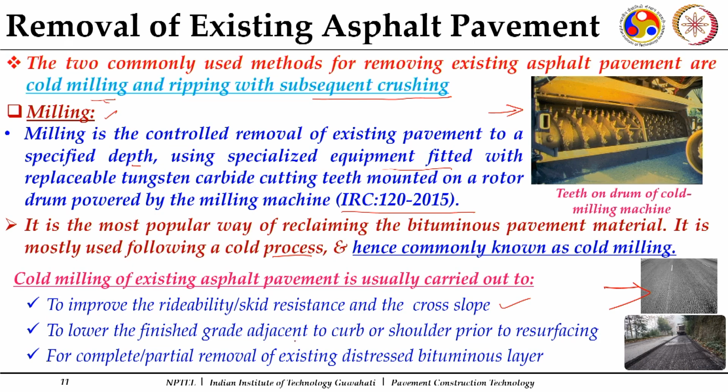Second, to lower the finished grade adjacent to curbs or shoulders prior to resurfacing. Many times, whenever an overlay or resurfacing is required, you find that some previous overlays are there and they are not as per grade. In that case, with milling operations, we can bring the existing surface to the required grade, so as to maintain a proper height with respect to your shoulders, medians and curbs. So this is another advantageous feature for which cold milling is widely popular.